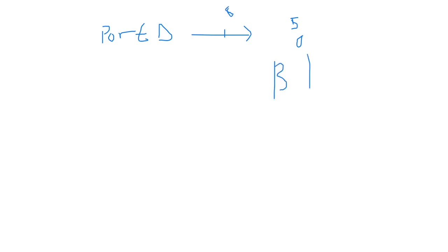So a few clarifications. Remember, we use port to write to that particular port. If it is write either 5 volts or a 0 volt to that particular pin, right? Now, if you write it to the whole port, it's going all the way to the whole 8-bit. But you can actually use a binary of 1010 to access individual pins. Is that clear, Bimbola? If that's a yes, you say yes.